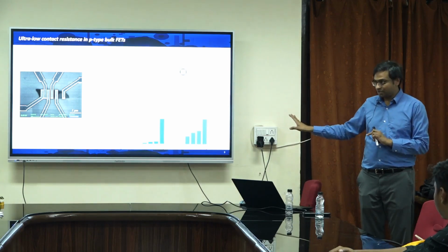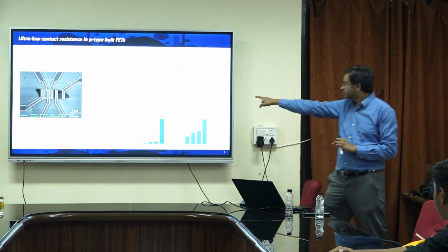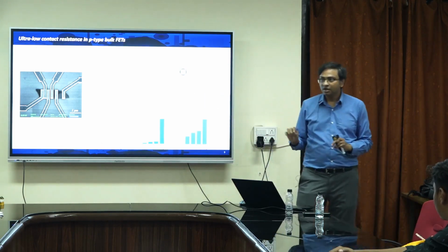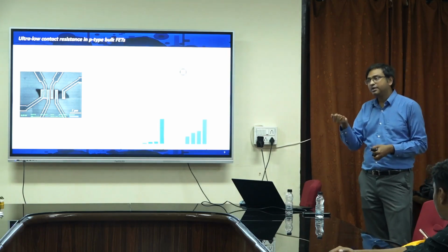That is established over here, right? Niobium is a good dopant. The next good one is probably tantalum, getting down to 180. Okay? So it is possible to get to very low contact resistance. That is solved. But then I now have to enable electrostatic control, right?